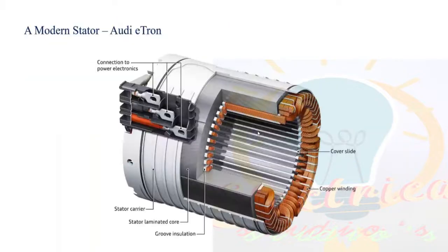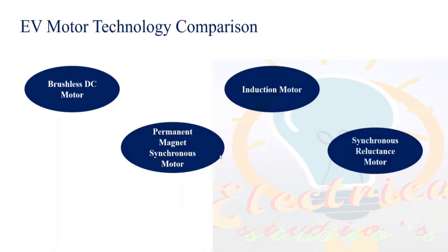And to make the work of the manufacturer easier, today what happened is, what are the two main components of a motor? Stator and the rotor. So now engineers, in order to make the electric drive more efficient, in order to make their designs quicker, have made the stator component common for all these motors. All these motors here, what I'm showing, brushless DC motor, PMSM, induction motor, synchronous reluctance motor, all these four motors, right now, design engineers are using the same or almost identical stators, right?